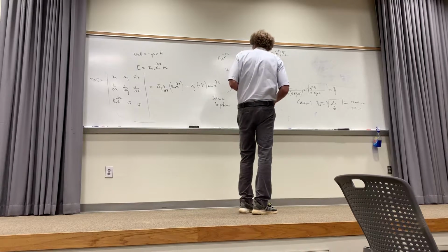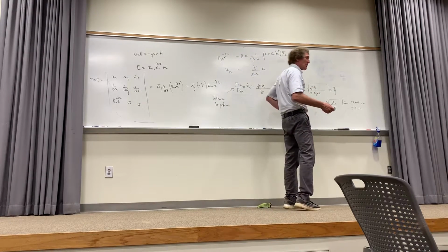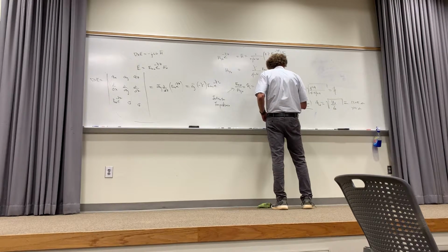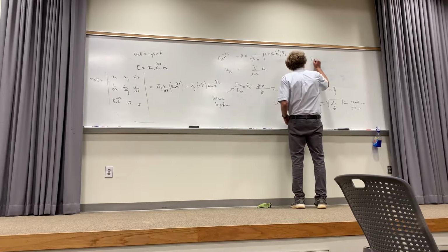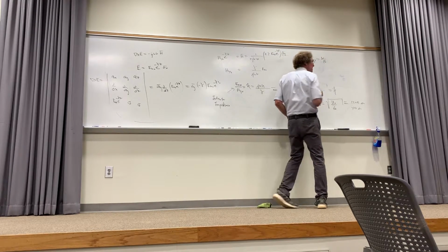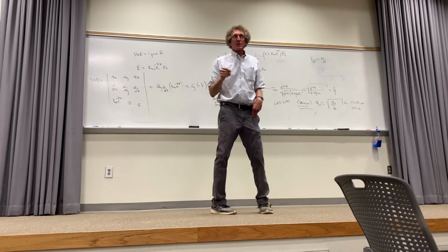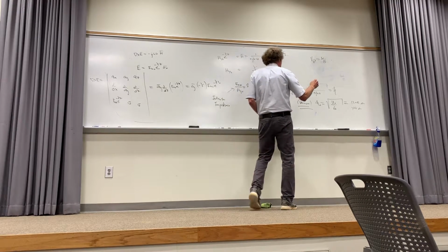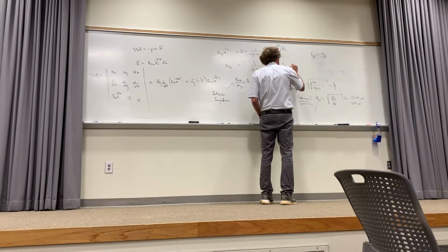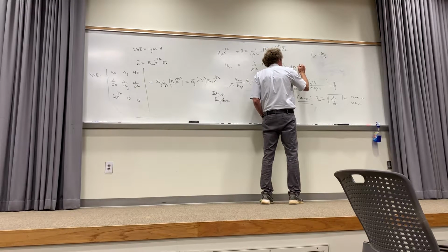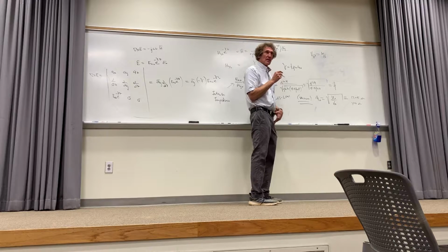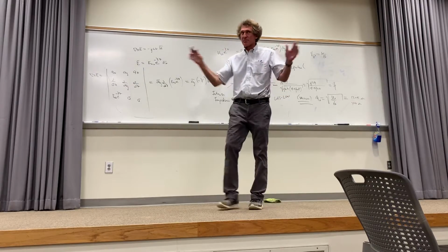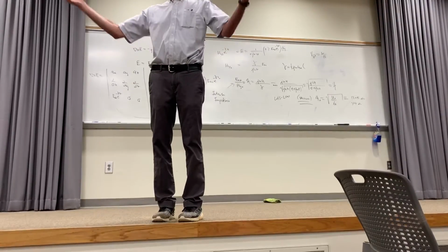Now, what you alluded to is the speed of light. Since we're on this topic of lossless, if you're in a vacuum or lossless, think about that. What was the phase velocity equal to? Omega over beta, right? You'll have to know these. In a vacuum, what is the propagation constant? Gamma is equal to the square root of j omega mu, which in a vacuum would be mu naught, correct, times sigma plus j omega epsilon. What is sigma's value in a vacuum? 0, yes, that's what I'm trying to get.